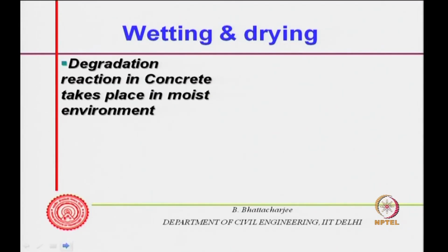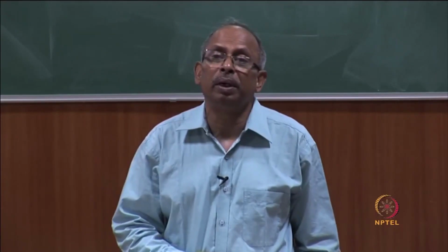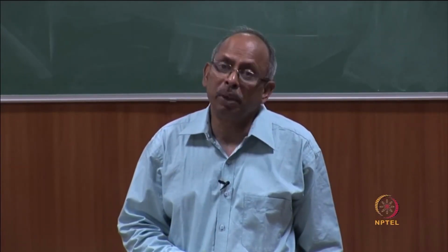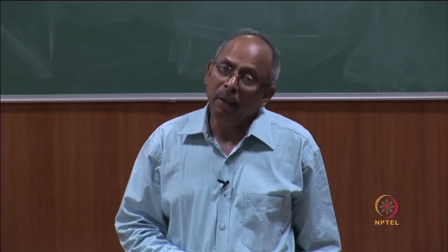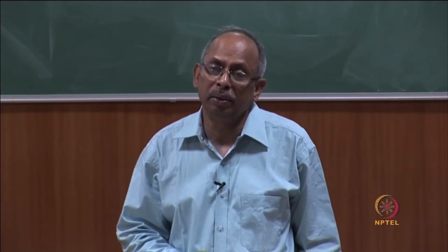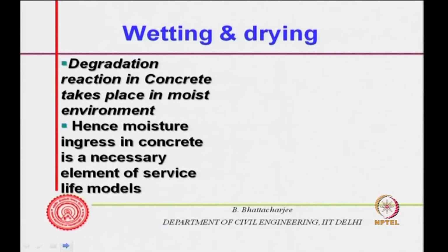Now, we already said the degradation reaction in concrete takes place in a moist environment, and concrete is not under fully saturated condition in tropical climate. Exposed concretes are subjected to wetting and drying. Even in western situations, colder climates and higher latitudes, concrete is under wetting and drying. Hence, moisture ingress of concrete is a necessary element in service life models. So, all models must look into this wetting and drying.